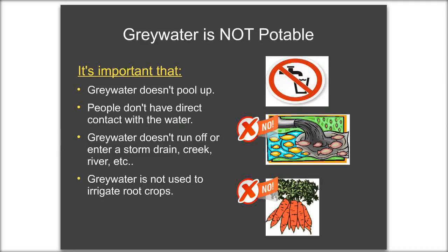So maybe some of those questions might get answered as we go through the systems, though we don't specifically address that. But you're right, you don't want to store graywater. If you store it, the nutrients will break down. It will start to smell bad. It will get kind of gross. You want to use graywater as soon as you can. Some of the systems have a tank to temporarily store it. We call it a surge tank. It's not storing it, it's just collecting the daily surges, and then usually it's a system that has a pump in it, and it pumps them out.